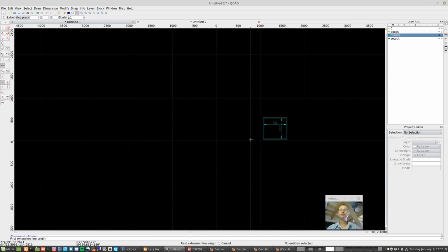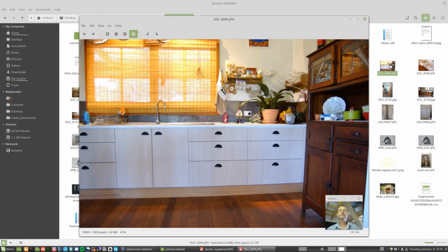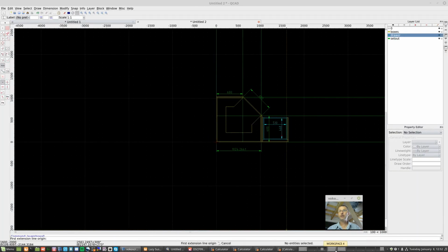Now with drawers, I'll just turn everything back on because I do a lot of them. I typically calculate whatever the heights of the fronts are, less 64mm, is what each drawer box is. So let's say you had 3 drawers, which is my typical drawer design. Let's see if I can find one in a hurry. So this is a typical set of drawers that you might have. There's a set of 3, staggering in height. And so how that relates to what we're doing is we have 3 drawers, take away 64. So 3 times 64 off the height.